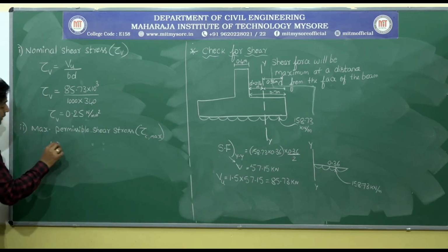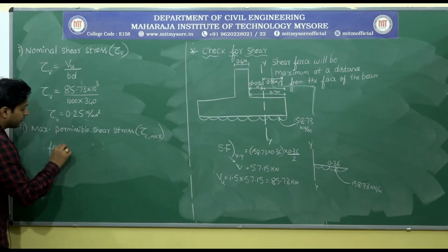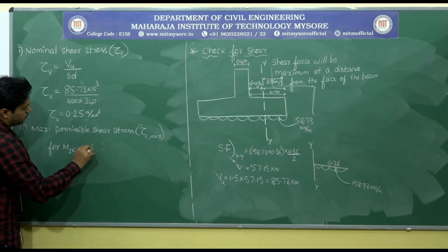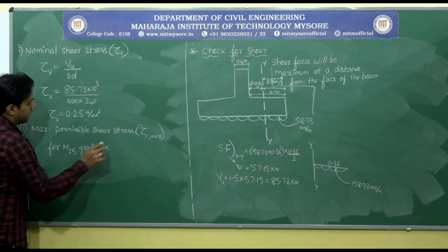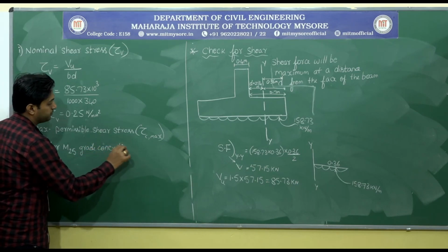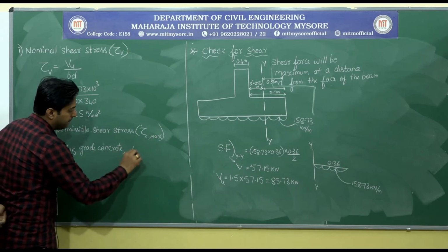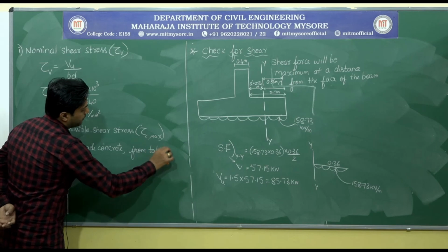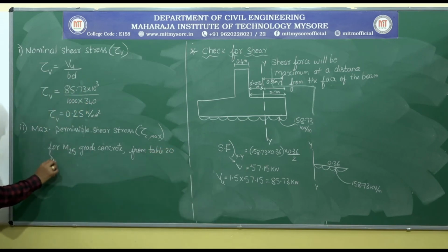For now it is not M20 grade, it is M25 grade concrete, from Table 20, page 73 of IS 456.